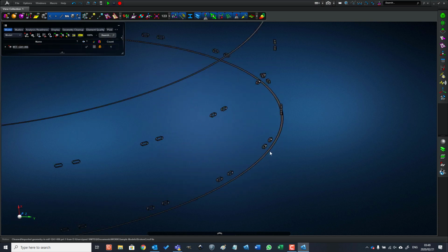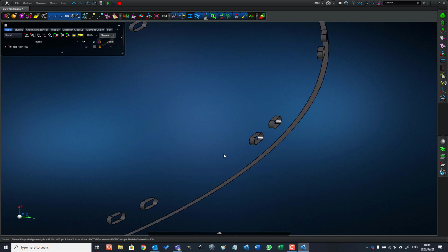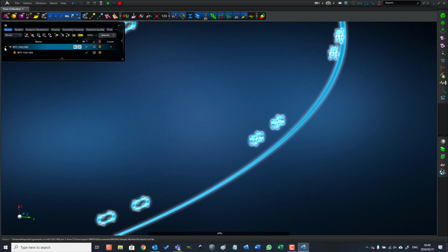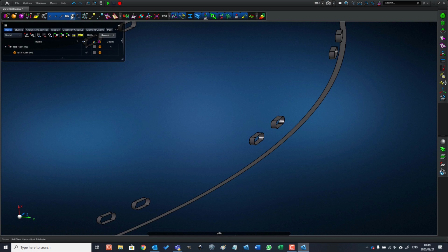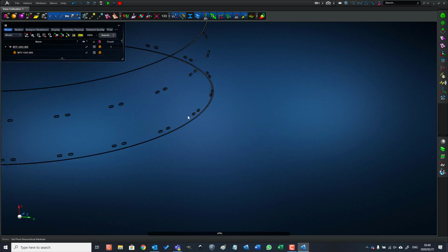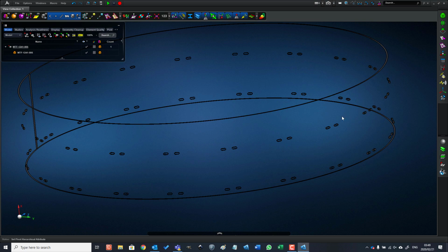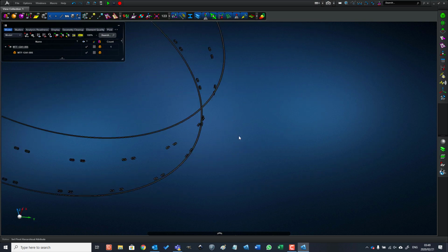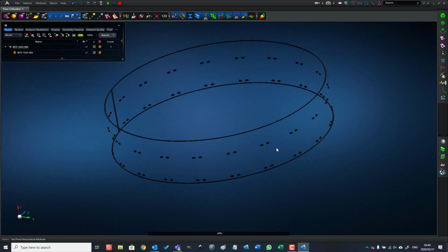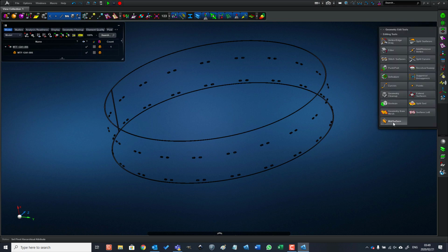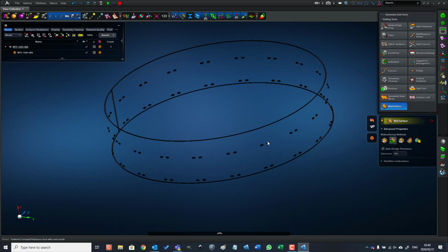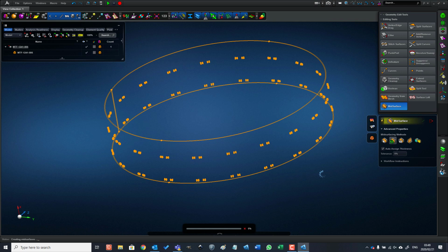It looks like a series of surfaces, although when selecting it and viewing it in the model tree, we see that it is indeed listed as a solid. This clearly indicates that there's something wrong with this particular solid. Let's test it by creating a mid-surface for that solid.